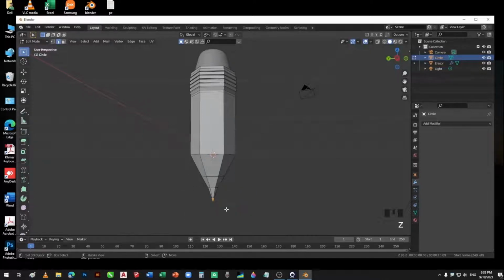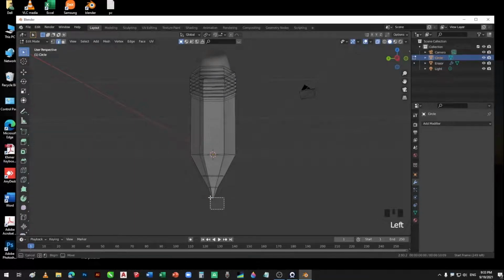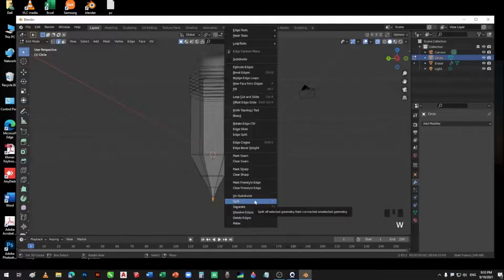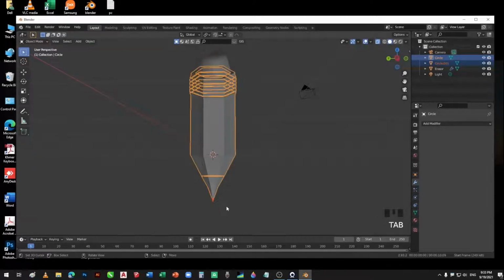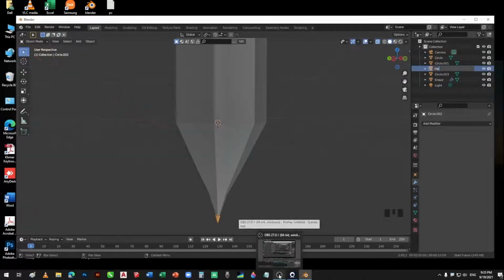As I mentioned, Blender uses the material for coloring, geometry modifying, and more. For this section we're going to practice the basics of the material. We will color the different parts of the pencil, therefore select the part and then separate the layer by pressing P as a shortcut, or right-click then separate and selection. Then rename the layers.